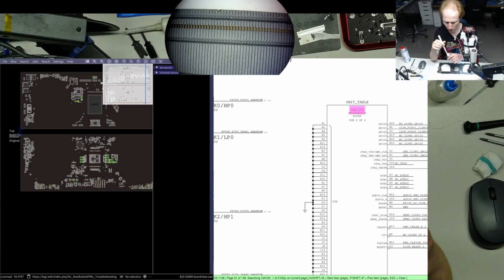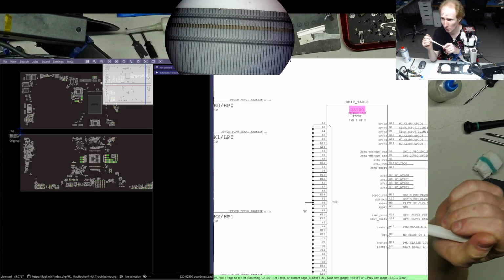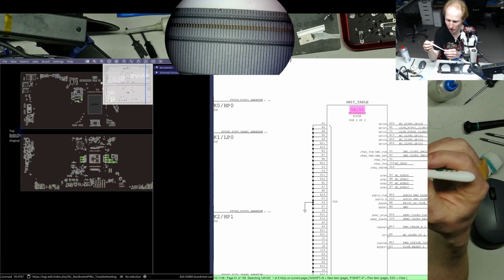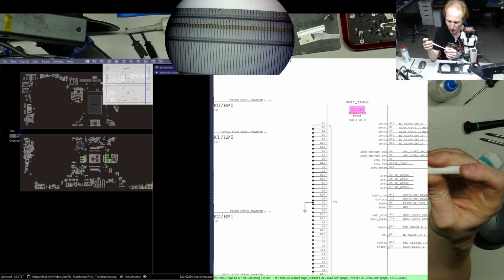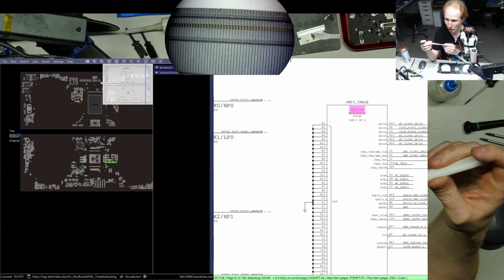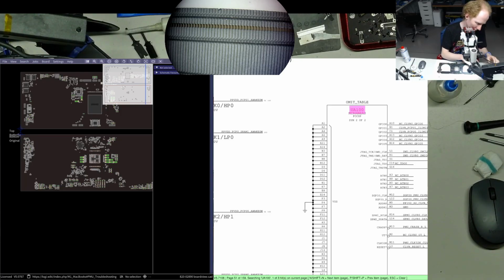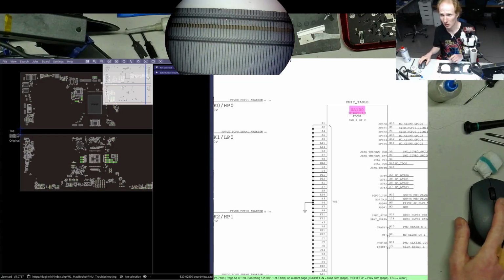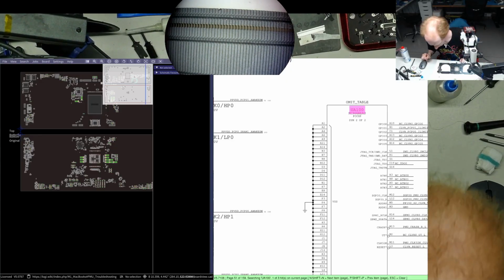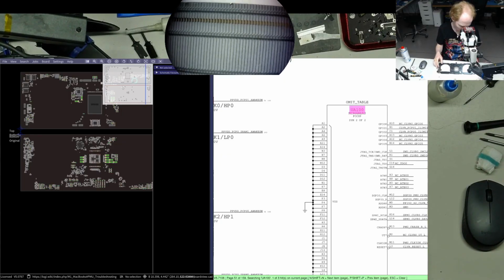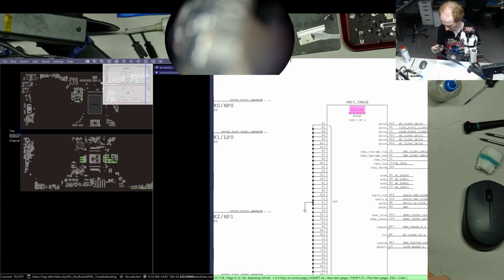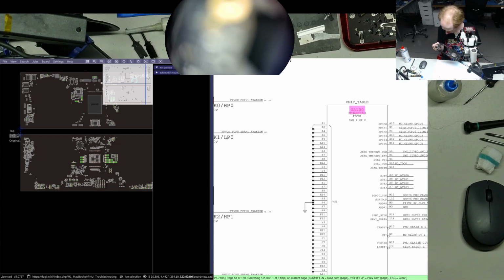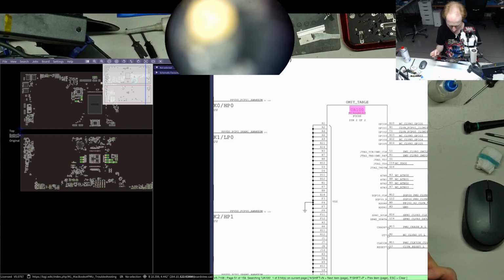So I thought this would be a very nice example of showing the logic analyzer method. You can use it for many different circuits, many different boards. It's not just for the audio. Basically, anywhere you have some communication lines, in our case this would be an I2C line, you can use it to figure out what's happening. The reason I need it is that there's been some soldering, I believe at least on one part, maybe on both sides of the board.